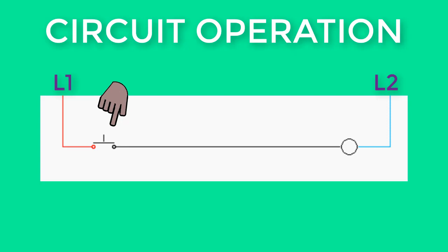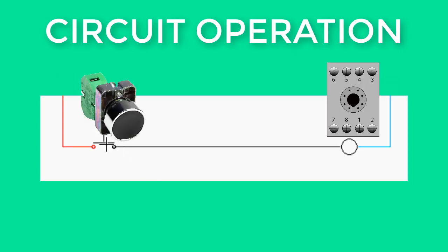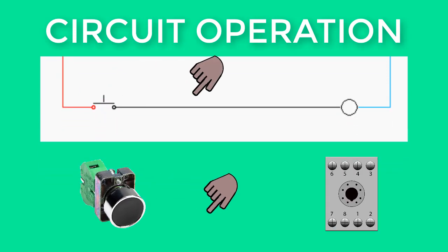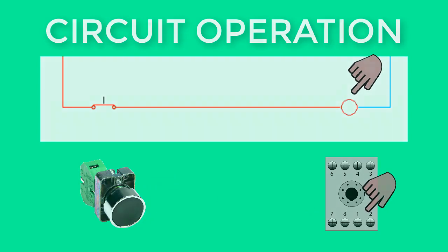In the circuit shown, a normally open push button operates a coil. The computer program allows a visual response of the circuit operation. Ladder logic design allows for circuit interpretation and for completion of field wiring, and also helps in troubleshooting control circuits.